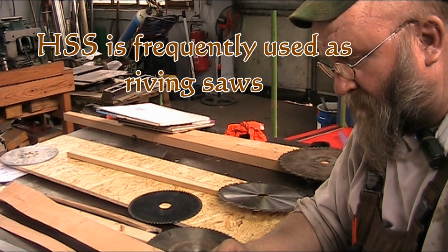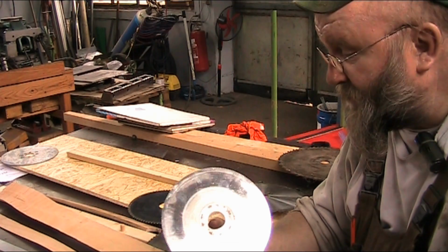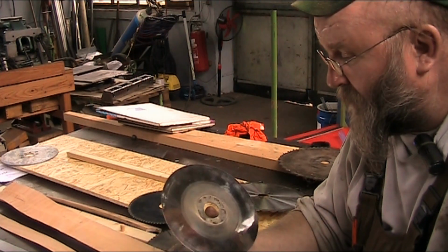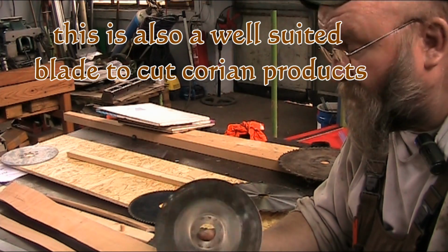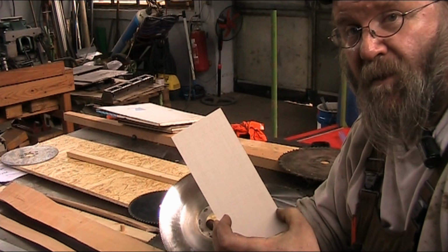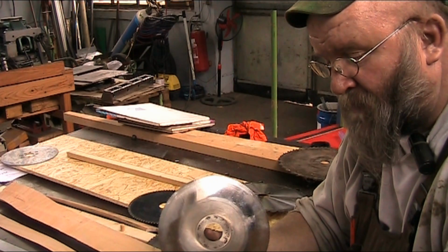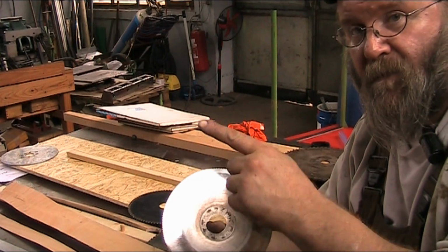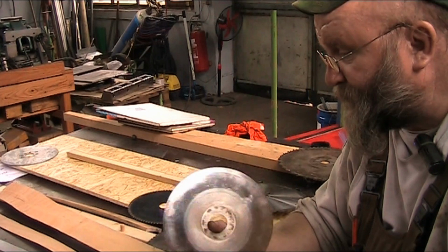And you don't see HSS in woodworking settings very often, but this is the one exception where you're going to see it. Normally HSS is reserved for steel and metals, sometimes plastics, depending on what kind of plastic you have. You can cut this melamine coated stuff with this kind of blade as well, because the HSS can take the abuse, although we have special blades for melamine coating. And I mentioned that over there at the whiteboard, so we'll get into that saw blade right shortly.